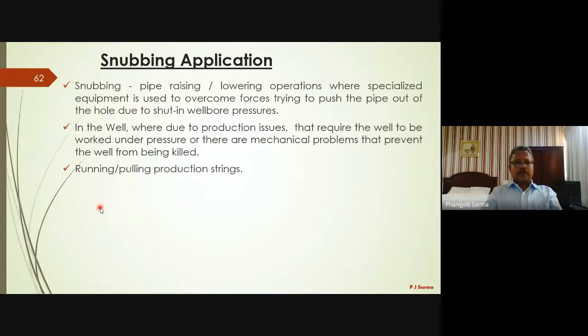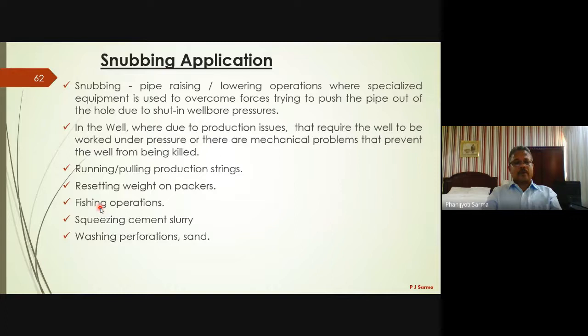So: running and pulling the string, resetting, weight on packers, fishing operations, cement squeeze, perforation wash. If the perforation is blocked with sand or scale deposition, the perforation can be washed. Installation of the velocity string, as I have shown in one of the pictures: a gas well is not getting produced because of water loading.